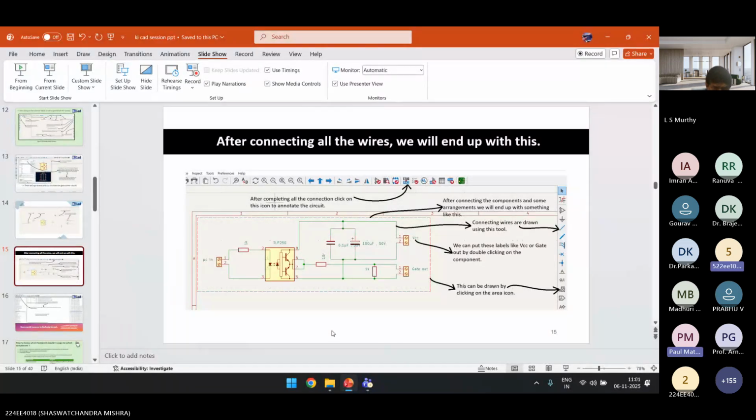Actually, there are other drivers available. This driver is perfect for a buck converter. Sorry, boost converter. Yeah, but it is isolated from the input to the output. So for a single individual triggering circuit, you can use TLP 250 also. If you see the configuration of TLP 250, it is isolated from the input and output. It gives an isolation from the microcontroller to the driver side, but the driver power supply should be shorted with the power converter supply.